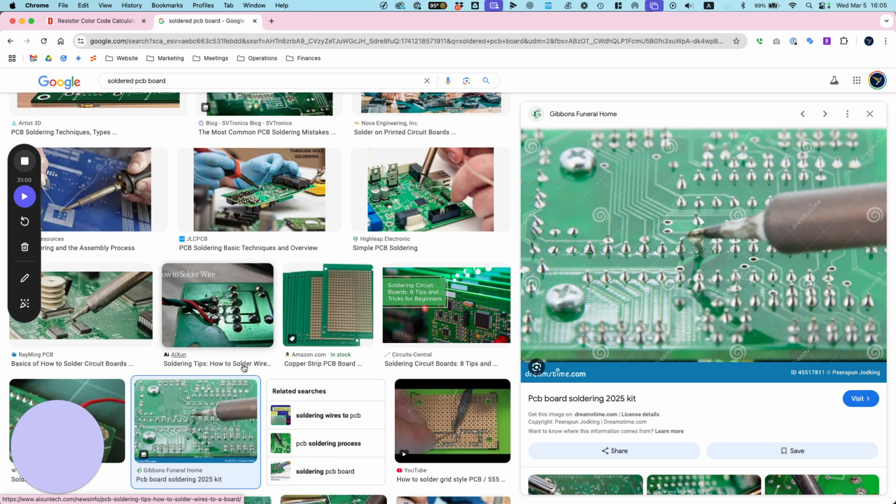Let me show one more thing here. When you come up to use this power bank, these wires are exposed. You see? If they touch, they're going to spark. So make sure, before you turn it on, that you are not crossing them over. Now I'm going to turn it on. Okay, and then our voltage that we want to use, you start low. This is the voltage knob, the very top one. And then you can incrementally increase it, okay?